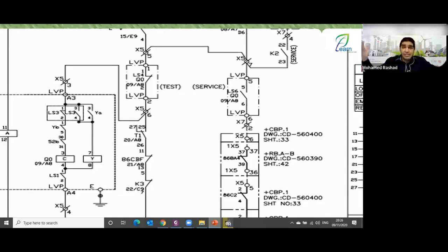This is a capacitor and its voltage is high, right or wrong? Now you've disconnected the circuit breaker. If you reconnect it, the capacitor has voltage and the bus bar has voltage. Closing both together will cause a large arc on your circuit breaker. So he wants to ensure that from the moment the circuit breaker is opened, a certain amount of time is waited. This time is recommended or provided by the manufacturer of the capacitor bank. It tells you not to close the breaker again before, for example, 1 or 2 minutes have passed.